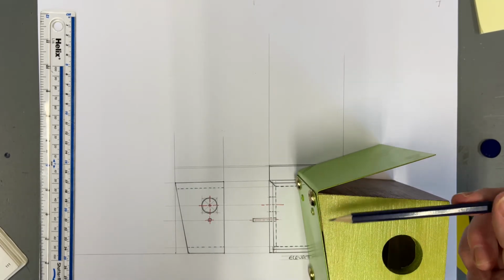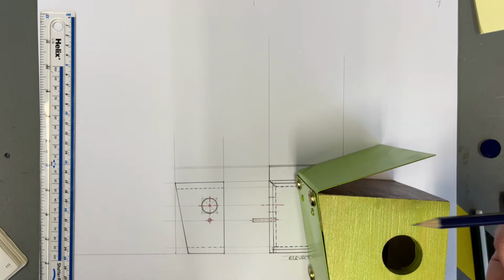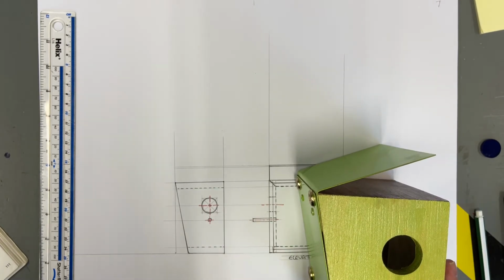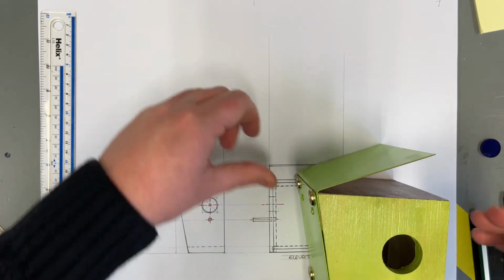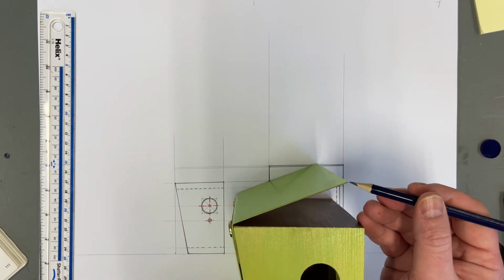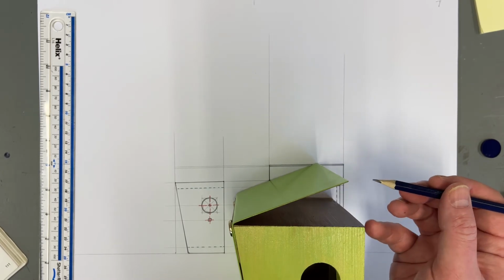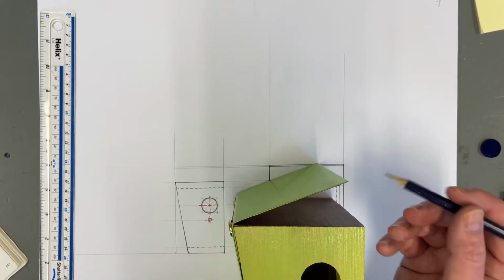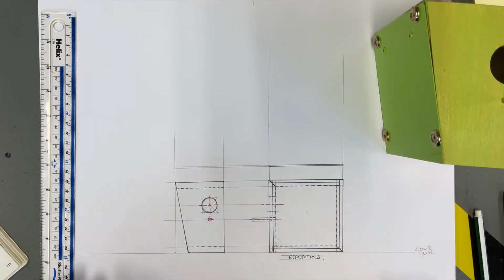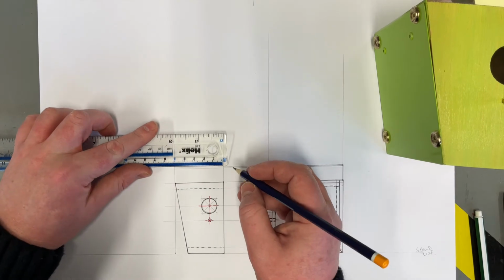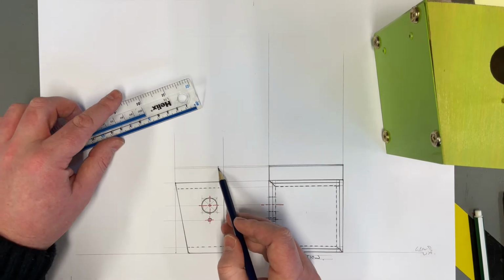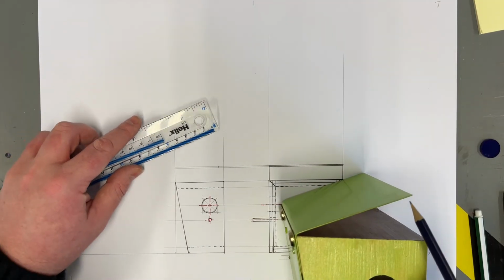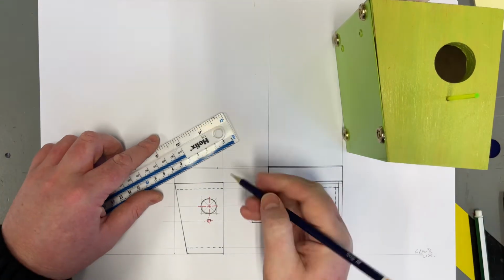We do want to add in the joints, but we don't want to be talking about overlapping 1mm lines. That just gets a wee bit too intricate. So in this instance, we know where the top corner is here, or rather should be, because if you follow the model, you can see that this is actually set into the side a little bit. And I reckon that's just about 10mm or so. So on the drawing, I'm going to come in by about 5 and decide that that's going to in actual fact be the top corner of the metal. I know that that's going to come down to the edge of the wood, so I can project the inside line.